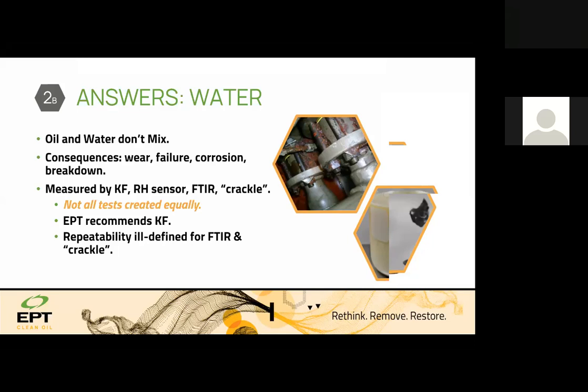Unfortunately, when we get an oil analysis report, some ASTM standard number is written there, but very few of us focus on which test is done by the lab. I will tell you 4 different methods of water testing in the oil, and now I will tell you what their differences are. The Karl Fischer titration test is the most precise, which is recommended for all critical assets.